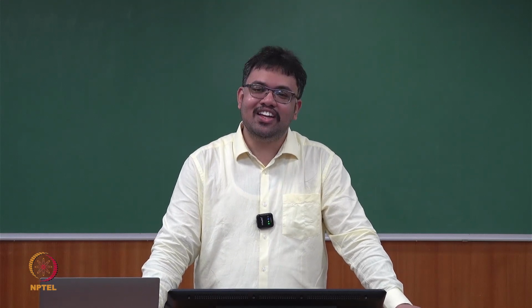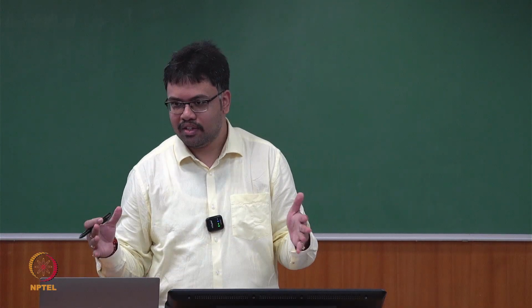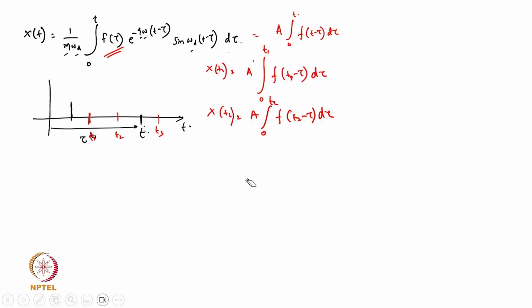Generally, these are recorded at 0.01 or 0.02 second intervals. Some stations may record 0.02, some may record 0.01. So we get some data set. More or less, standard earthquake records come around 40 seconds, and mostly if it is measured at 0.01 second, you will have 4000 data points. So the total response can be calculated this way.